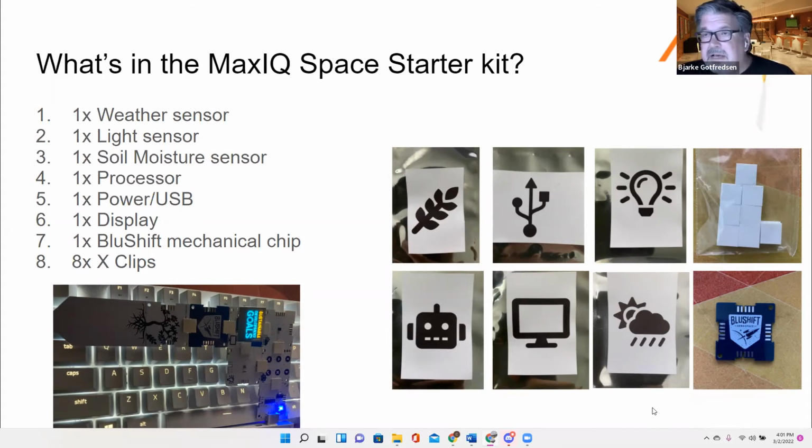Typically with light sensors, UV sensors don't include UVC, because we don't have UVC here on Earth; it gets absorbed before it comes down to us. And of course, a lot of these sensors are not built for research or satellite use. They're mostly built to plug into a cell phone or something like that, where they're being used in the millions.